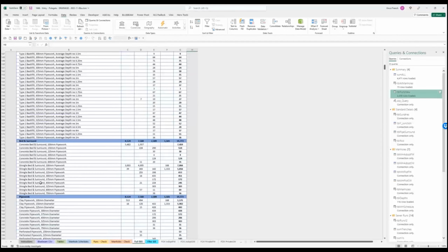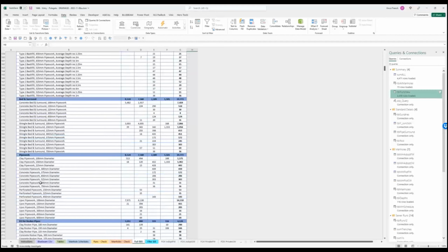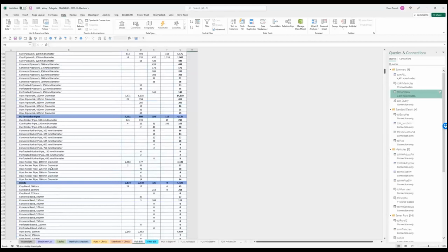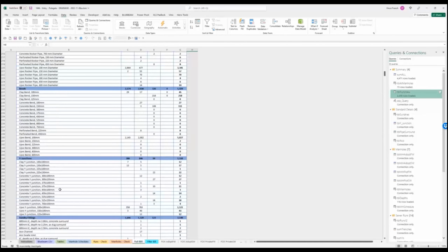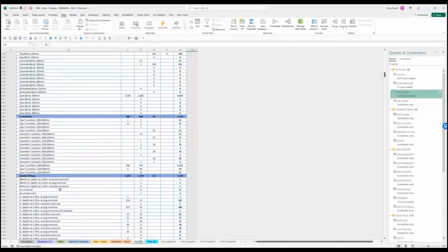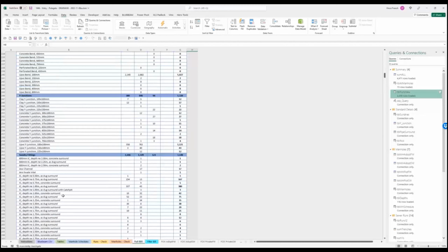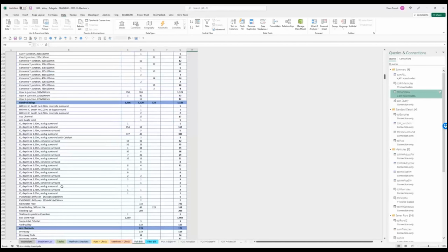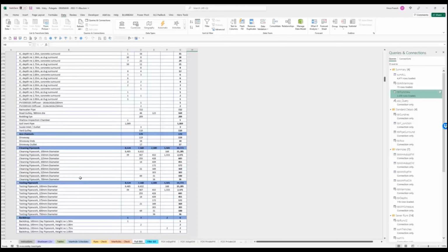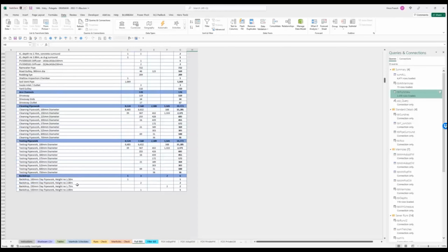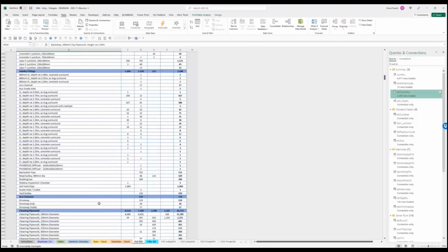We've got all our concrete bed and surrounds, shingle bed and surrounds, types of pipe work, rocker pipes, bends that are needed, wide junctions where we're joining onto runs, all our sundry fittings, and cleaning pipe work, testing pipe work. In backdrops to the manholes, we've got all the details created automatically.